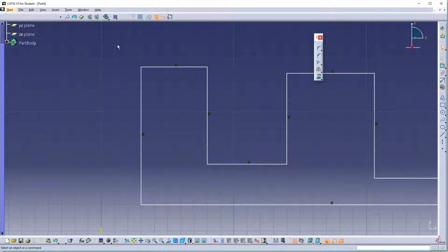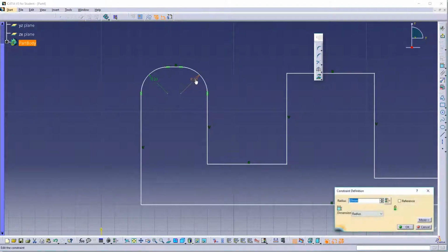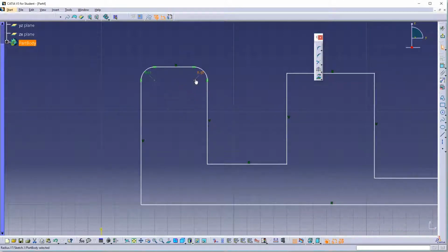Now let's say that you multi-select by selecting and dragging there. Now what I've multi-selected is actually the line and those two endpoints. And if I pick the corner option now, obviously there you can barely see the two endpoints are still highlighted. And my mouse really isn't doing anything, but if I key in 20 again, notice it's keying in up at the menu bar, then I get both radiuses, and in fact, if I change one to 10, they're both linked together as a function.